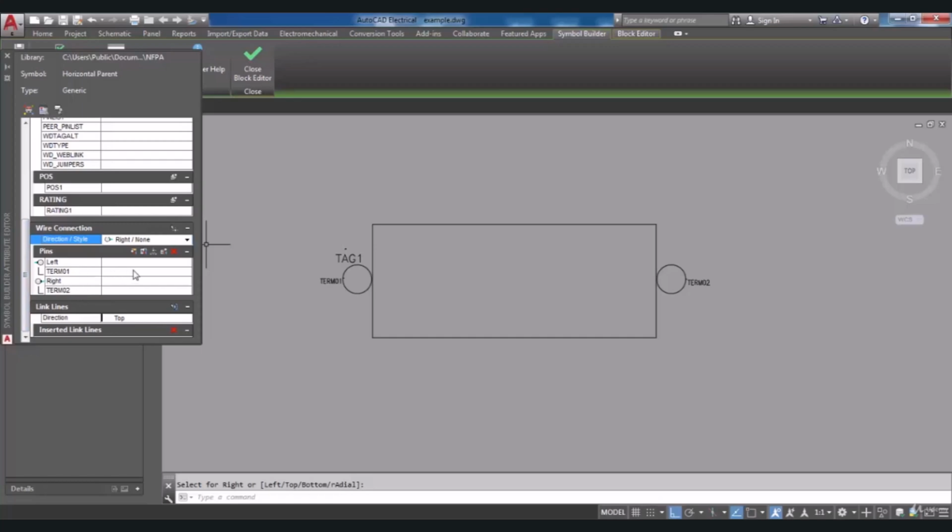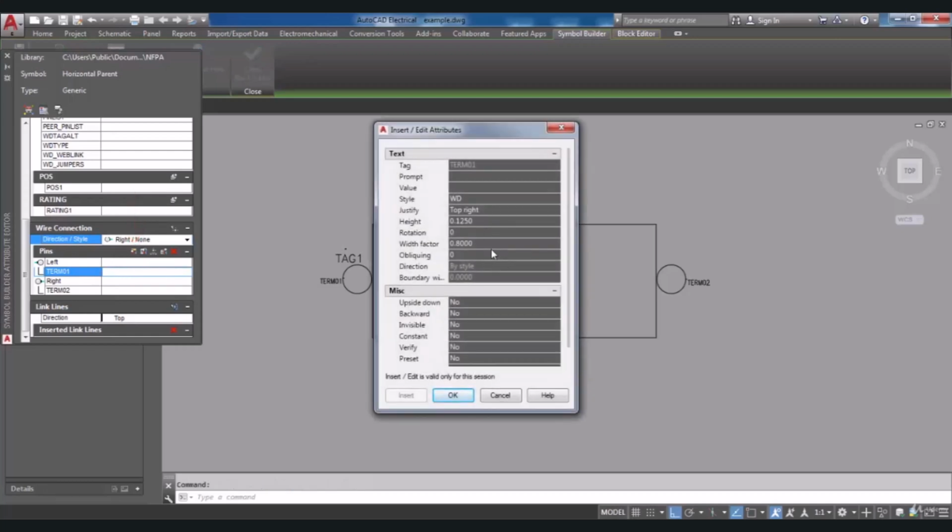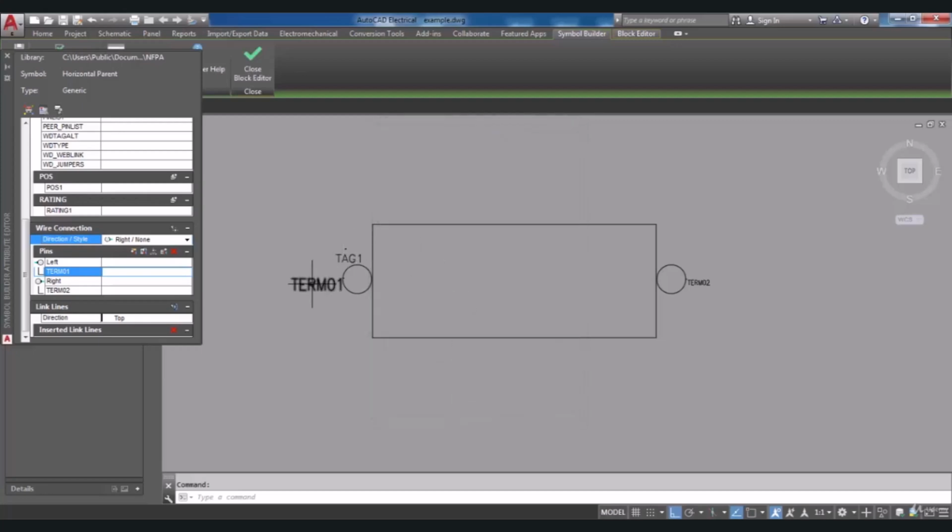Also, you may need to change the size of every pin's connection text. In order to do that, you can just click on every text and the pins are selected, and then select the Properties button beside Pins. And this is set by editing the height of the text area and finally choosing the OK button. The size of the text will change.